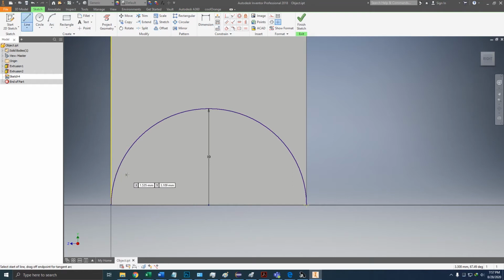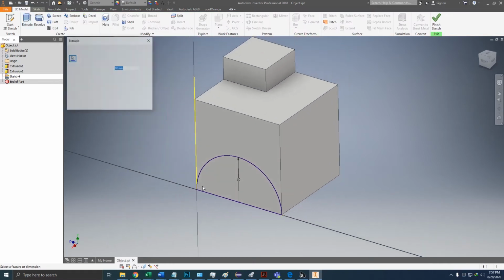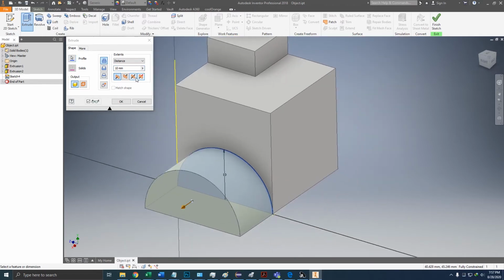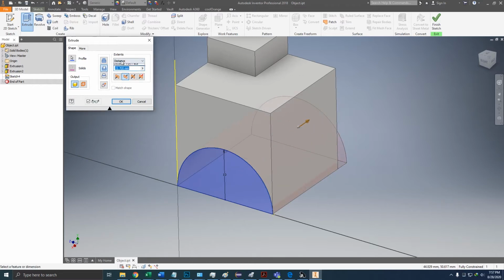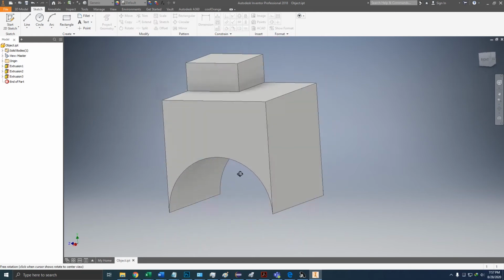And then before you extrude, the sketches have to be completed like a closed loop. So I'm gonna use the line tool and connect these two corners and click escape. Now this is a closed loop and you can extrude it. So to do that, go to 3D model, extrude, click on, sometimes you have to click on the part that you want to extrude and use the controls showed in episode 1. So that was a piece cut out just like that.